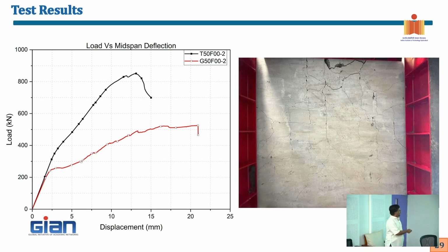See, if I increase the rebar, you see here, right? After cracking, it is all the same. The moment it cracks, the stiffness is lost. And as expected, GFRP has less stiffness. We know that if I replace it with the same rebar.